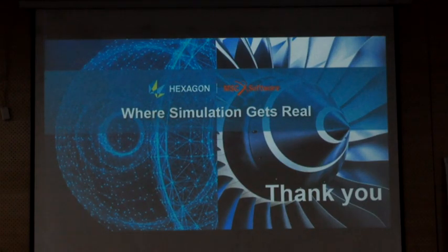Yes. Sir, you talked about the process simulation. Which type of process? I mean, basically, is it LPBF or are you simulating other ones also? Other also. There are 6 to 7. I can simulate FDM, SLA, DED, LPBF, then binder jetting. These are different modules because in the background, the science is different. The material we use, in DED we use wire or powder. In LPBF we use powder. Then SLA and FDM we use plastic. So these are different modules we have to choose based on the application. The same design, you can put into all of these and understand which is better. That also you can do.